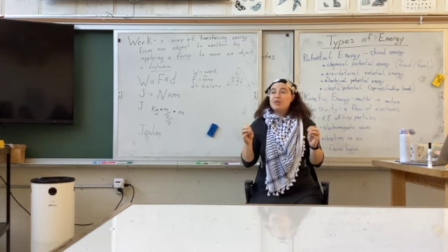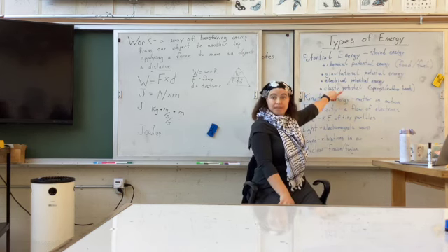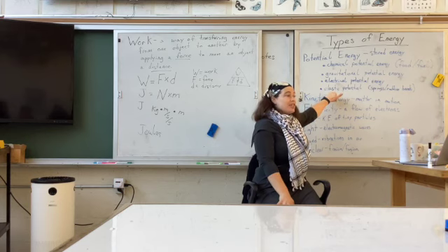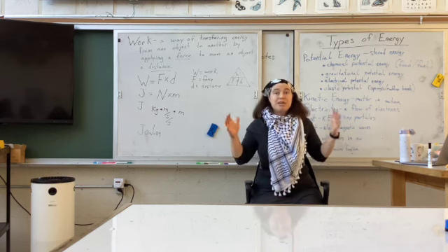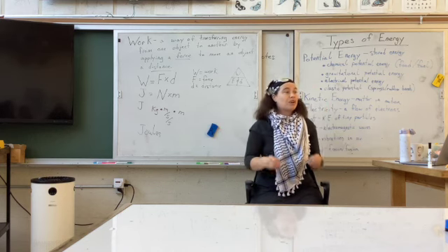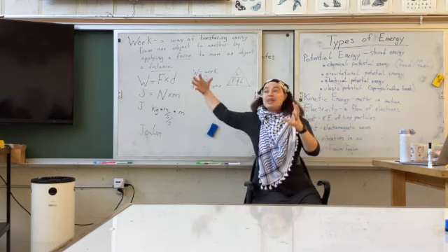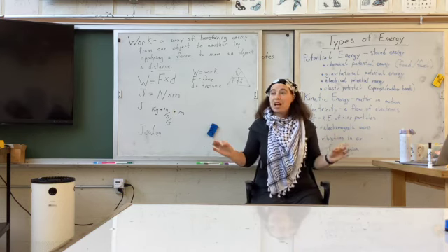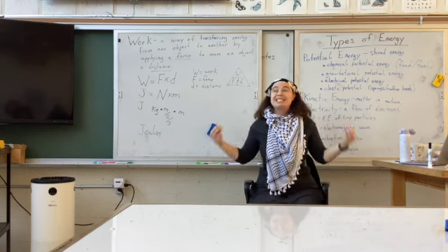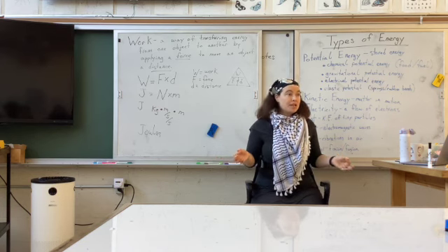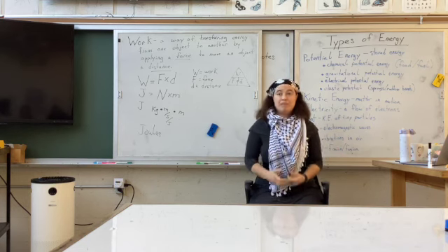What we're going to do is use that same amount of energy. There's elastic potential energy stored in that spring. And we're going to use that elastic potential energy to do the same amount of work that it would do if it was killing a mouse. But instead of applying a big force over a short distance, we want to apply a tiny force over a really big distance. Because your goal in this project is to make this car travel as far as possible. So we're going to go a big distance with your mousetrap cars. But you don't need much force, right? You just need enough force to make this car accelerate even a little bit.